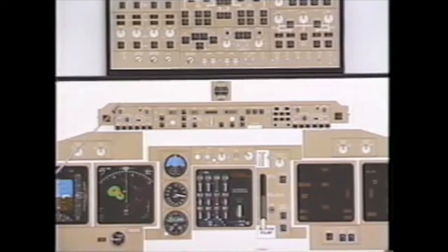Specifically on the EFIS control panel, we have a decision height and MDA option. Decision heights are radio altitudes displayed in the lower right-hand corner of the attitude indicator. MDAs are MSL altitudes and are displayed in the upper right-hand corner of the attitude indicator. SOP is to select one or the other. Do not have both displayed.